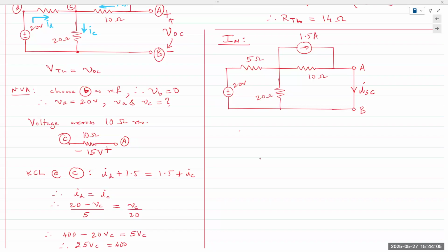Well, that's true. But I was just thinking in general terms. When we do circuit analysis, what is it we're trying to do? We're trying to solve for unknown quantities, right? Values for unknown quantities. Meaning mathematically, we are writing equations. Equations have unknown variables. And so the lesser number of unknown variables we have, the fewer equations we have to write. So we count the unknown nodes and we count the unknown meshes in the circuit. Whichever is less is our go-to answer.